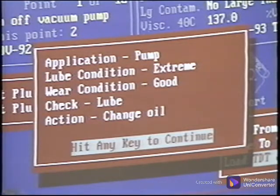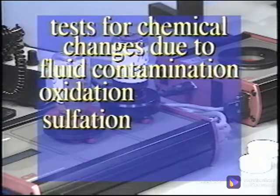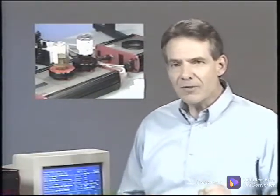This analyzer provides a good indicator of any chemical changes that result from soluble fluid contamination, increased acidity, the occurrence of oxidation, sulfation, and nitration, as well as the presence of soot. The on-site tests for lube quality provide instant results assuring you of the vital functions of the lubricant.